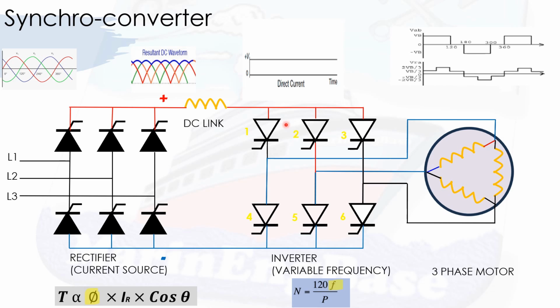The output of this three-phase bridge will be something similar to this diagram. We call it a quasi-wave pattern or six-step waveform. The fundamentals behind producing such a waveform I will speak about in a different lesson. There I'll explain how exactly this frequency is produced, in which sequence you have to fire, and at what time intervals for each pair.